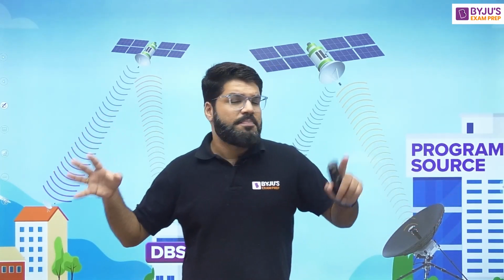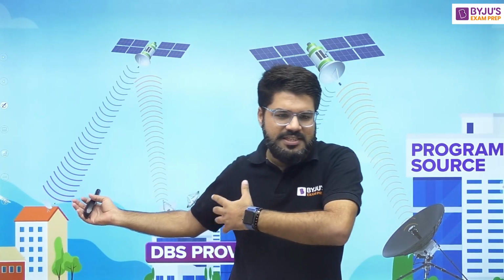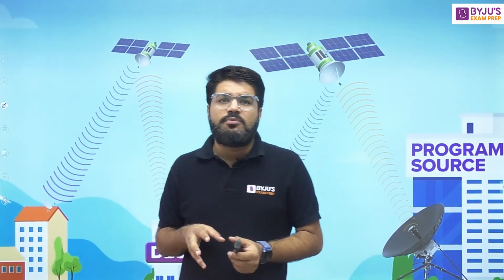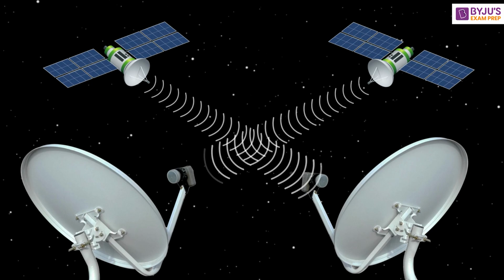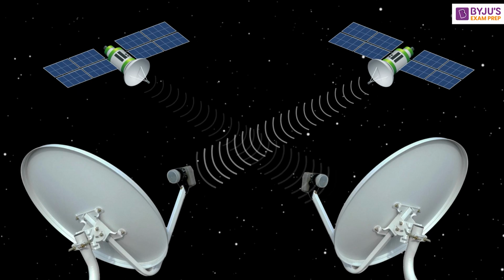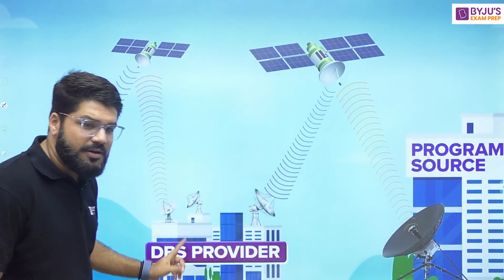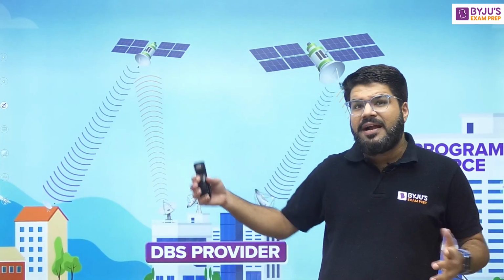But the very important point is that the antenna you install, maybe on the terrace or on the balcony, has to be angled in a direction corresponding to the transponder, right? You can just go out, guys, and check it out. As a simple fact, go to your locality and you may find one Dish TV antenna, one Tata Sky antenna, one Airtel antenna, the receiving antenna I'm talking about. Within the same locality, they may be angled and positioned differently, because every parabolic receiving antenna has to be angled in a direction corresponding to the transponder of that particular DBS provider. So you can just check that out outside.